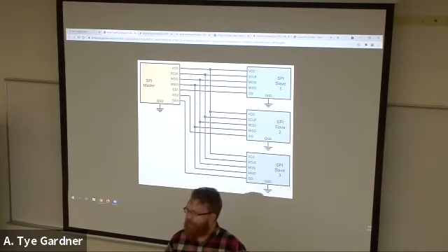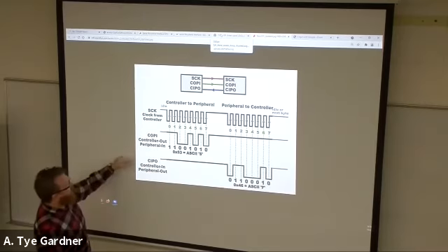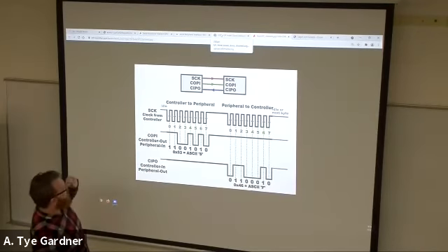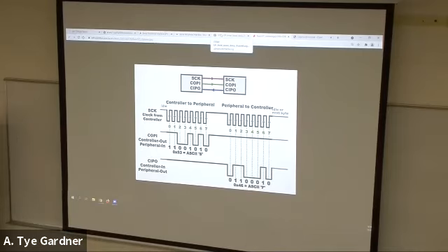So there are several different versions of the protocol for SPI. In fact, there are 4. This one is back to COPI and CIPO, which I'm never going to remember, but I will try for the sake of the modern generations. So here we have clock, right? It's just going to have a rising edge for each and every bit that it wants to transmit. This is really terrible. Why doesn't it have the chip select? I don't want the chip select.